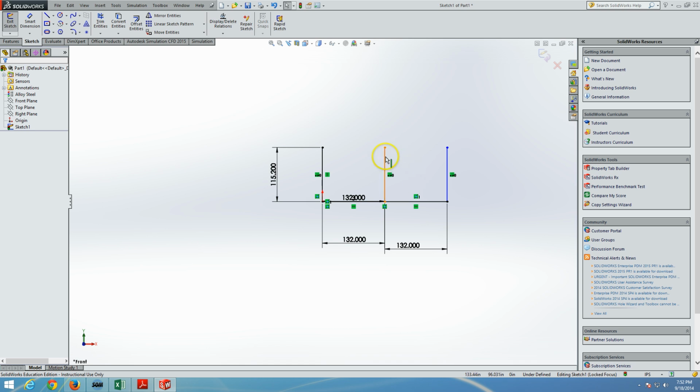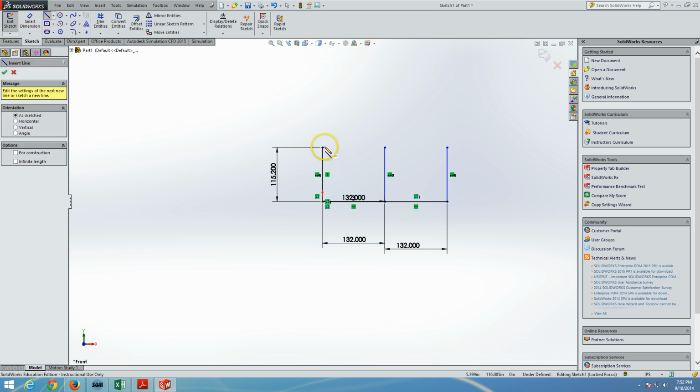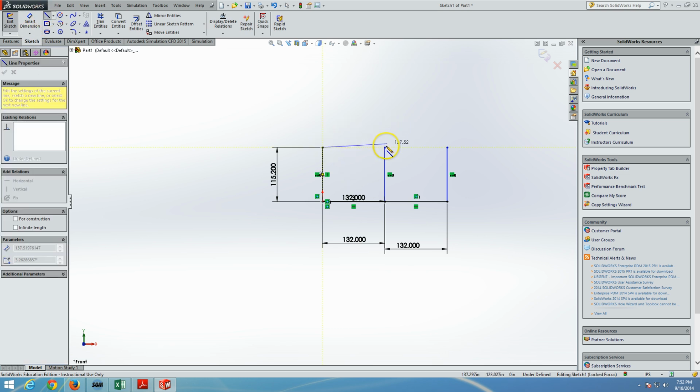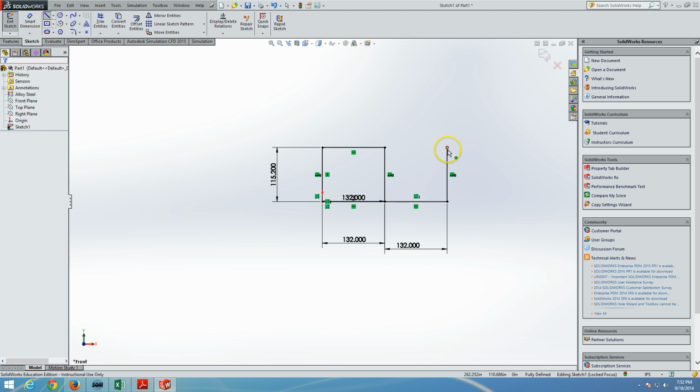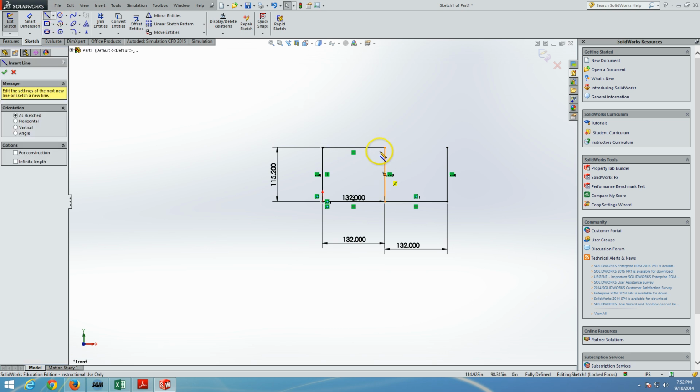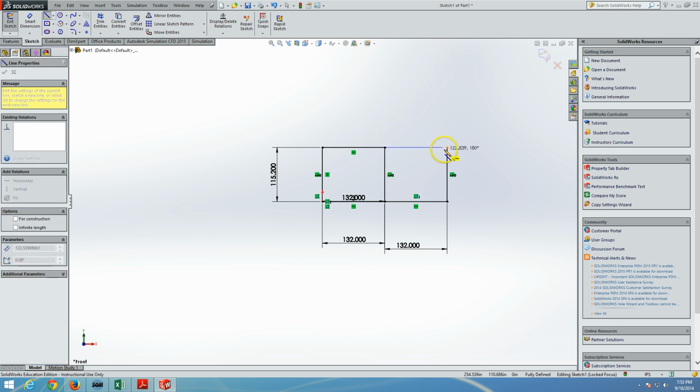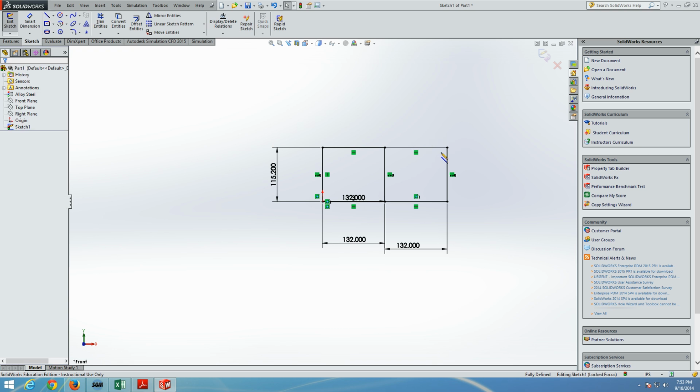Here are our lines. They are defined, that's fine. Now we can put the top lines to close them, and we can put another line segment from here. It's of crucial importance not to draw long lines. Each physical segment needs to be represented by one line of the determined length. Otherwise it will become a beam model, not the truss model.